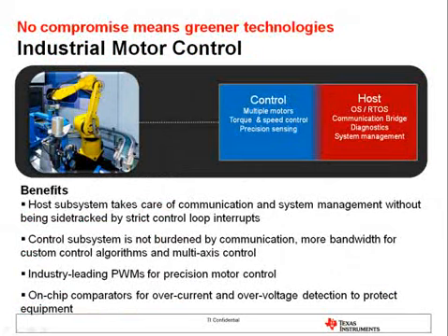So what does this mean in a real system? Let's take a look at industrial drives and automation. A significant portion of the world's energy consumption is used by electric motors. Sheer volume contributes to this, but so does the fact that many of these motors are open-loop motors that run at full power 100% of the time. Adding intelligence and closed-loop control allows these motors to be controlled more efficiently, where they consume only a fraction of the maximum power under light load conditions.